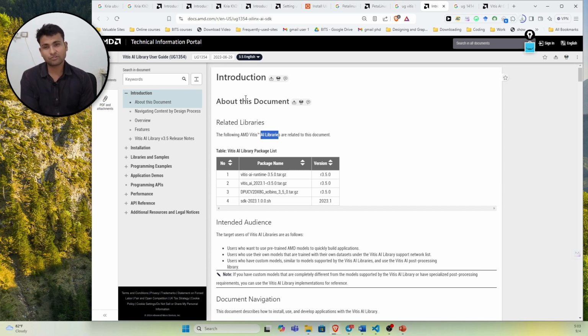But after Ubuntu, Petalinux has gone a little into legacy mode, and Ubuntu is more unanimously accepted, with all the libraries and everything available on it very easily. Starting from the Kria boards, Kria K26, they have started to release an Ubuntu package. So we have an Ubuntu operating system, and on that we can load any of the hardware acceleration kernels which we want to write, and accelerate them along with running our operating system.